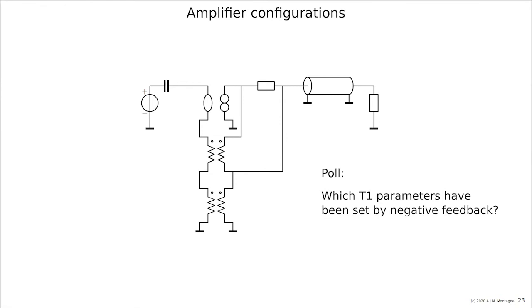Parameters C and D are both 0 because C is the transimpedance gain of the amplifier, which means you are going to put a current in and see what will be the voltage out. But if you try to put a current in this amplifier, it cannot be allowed because there is a nullator at the input, so the input voltage will immediately rise to infinity, which makes C 0. Similar can be said about D. So C and D are both 0 and A and B are set by feedback.